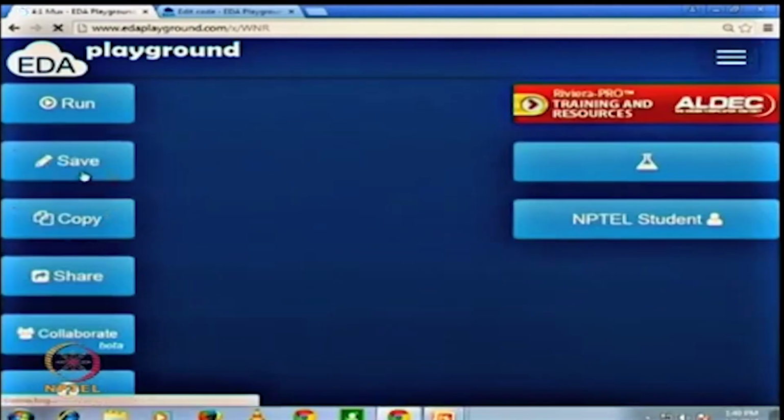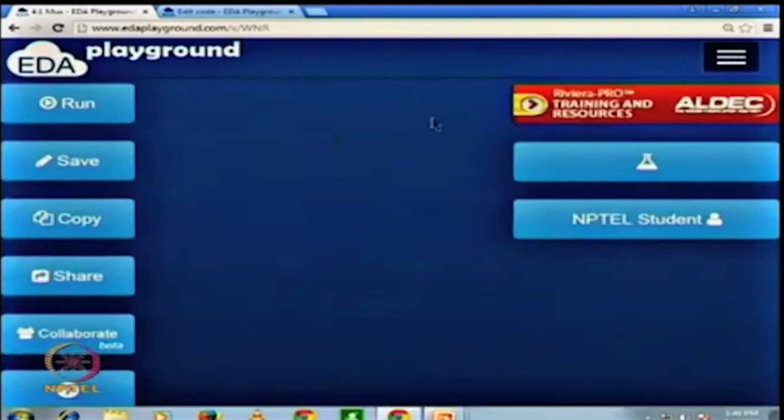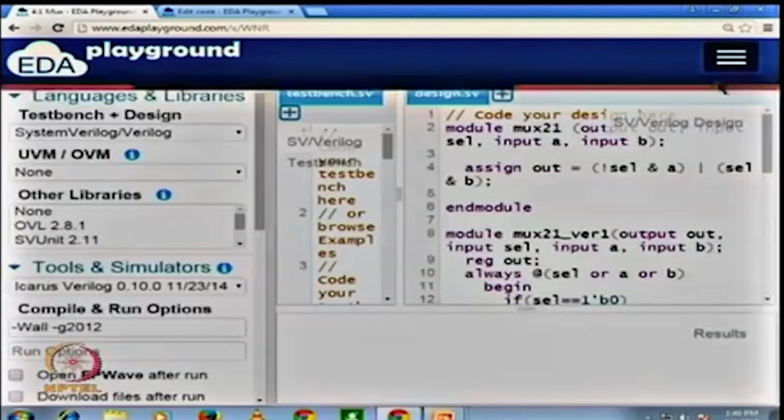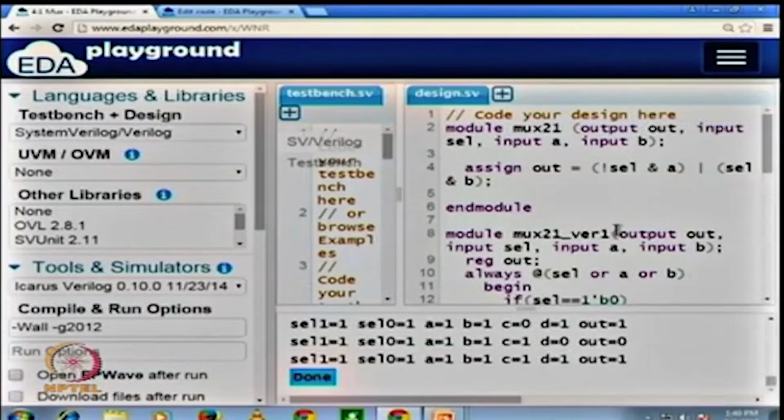So Verilog allows you to mix and match different things, and what we have is what are called different architectures for the same design. If you know VHDL, the MUX21 is an entity, and we have three different architectures. Verilog does not give you the same facility as entity and architecture like VHDL does.